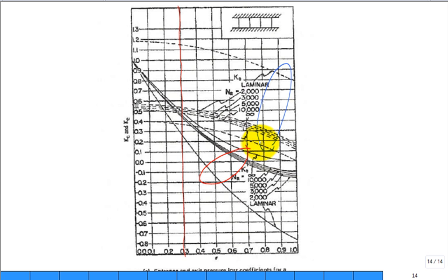And it ranges between laminar flow, the curve that's the highest, to infinity, that's this curve right here. And here's 2,000 and 3,000, 5,000, 10,000, and then Reynolds number of infinity. So for Reynolds number of 600, what curve do we go to? Laminar. So we find the intersection of 0.3 for sigma with the laminar curve.